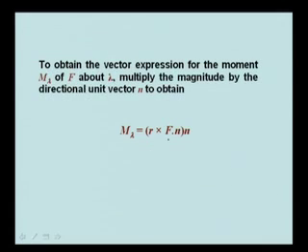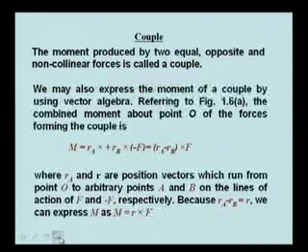is equal to R cross F. R cross F is a vector, that is basically m0. Then you take the dot product with n, that is m0 dot n, and this is the magnitude, and the direction is the same as the direction of that lambda. So, therefore, we attach n here. R cross F dot n is a scalar quantity and n is this one. So, this is a moment about an arbitrary axis, this one.